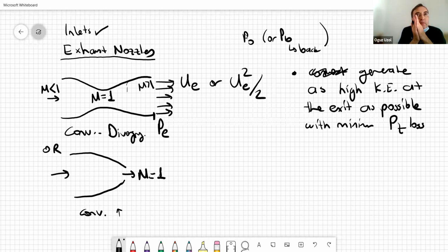How does it know that? Because there is no choking. Huh? There's no choking of the throat if it's entirely subsonic. I'm talking about back pressure. Choking is upstream. But once it gets choked, then it has no information about what's happening at the back. So if it's subsonic, the back pressure information is propagated with speed of sound. That speed of sound waves reach the nozzle. They can reach because nozzle is exiting at subsonic speeds. Information is oncoming at sonic speed. So nozzle always knows what the back pressure is. So it also always keeps equal.